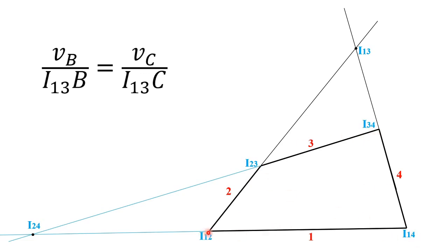Now, which is your crank? Usually this link 2 will be your crank. So as the crank rotates, B will move, right? C will also move. And what is your input then? Input is crank velocity. What is your output? Output will be rocker velocity. So imagine this is a crank rocker mechanism. What is rocker velocity actually? You have 2 points in the rocker, C and D. D velocity is not the answer because D is a fixed point. So the velocity of C will be your rocker velocity, right?